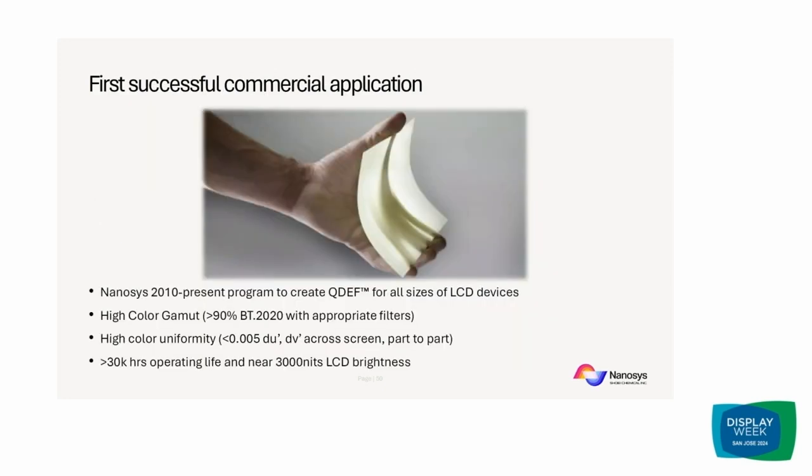QDEF was, in fact, the first very successful commercial application that came from quantum dots. Structurally, it is a film, typically PET, or polyethylene terephthalate, on the outside, with quantum dots on the inside. This has been a program from Nanosys all the way from 2010 to today, with continuous improvement to be able to make QDEF for every potential size of LCD display.